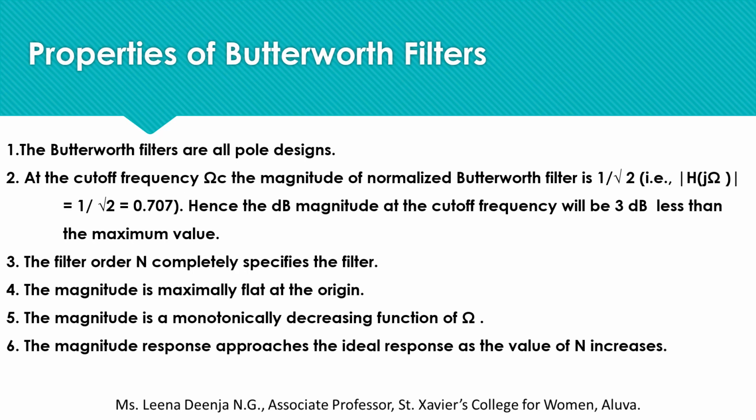Third property, the filter order N completely specifies the filter. Fourth one, the magnitude is maximally flat at the origin. Fifth property, the magnitude is a monotonically decreasing function of ω. Sixth one, the magnitude response approaches the ideal response as the value of N increases.